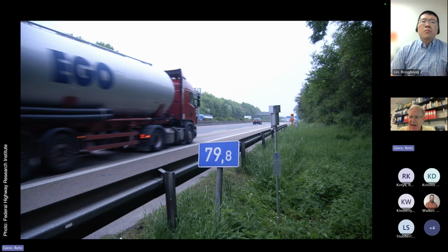So what I want to show you now is how we actually characterize this. What you see here is a sampling station along a German highway. Here is what is known as a passive sampler. There's no pump in here, but we can collect air samples, basically particles in the air. The air flows through this sampler and is passively collected inside this collecting device. The air goes in here. It is not a turbulent flow.